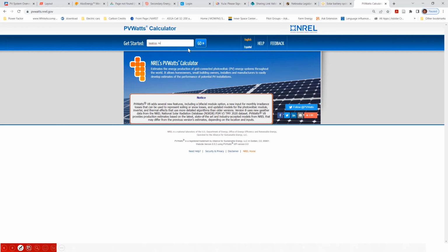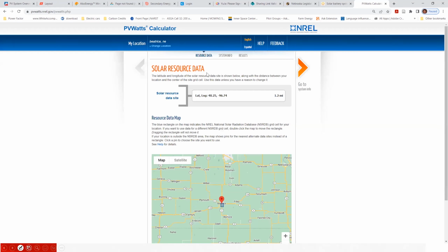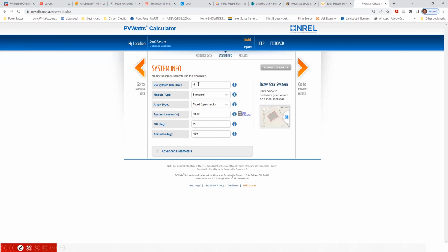I'm just going to put in Beatrice, Nebraska as just a place. You don't have to search your address. You could just search your town. That's going to get you close enough. But you need to search your town because it's pulling a weather file from that location. And you want the weather file that's within about 10 miles of you to get a good quality weather file pulled. So search the town you're in, and then you're going to go and tell it how big the system is.